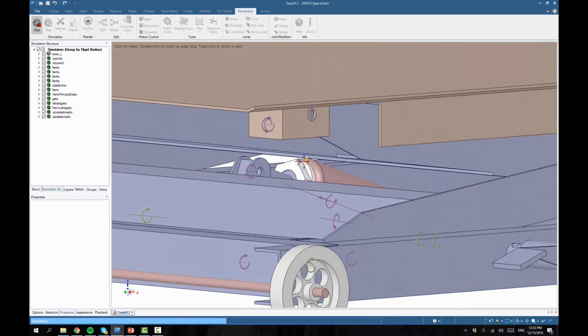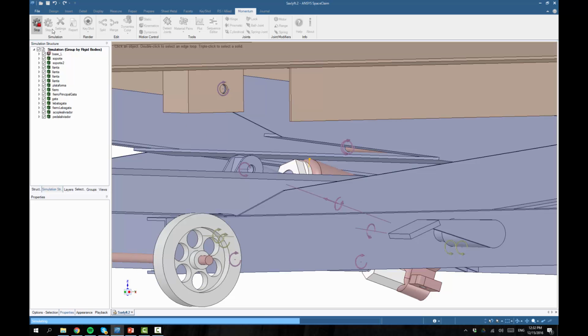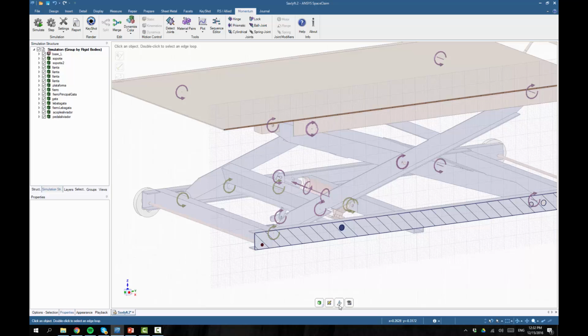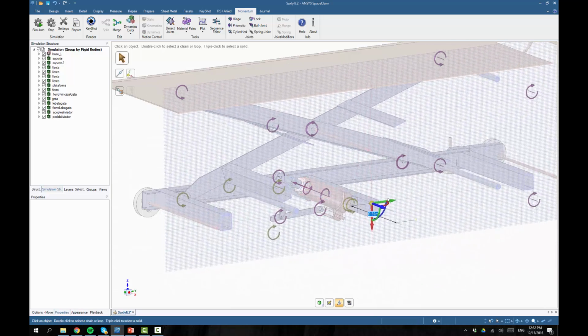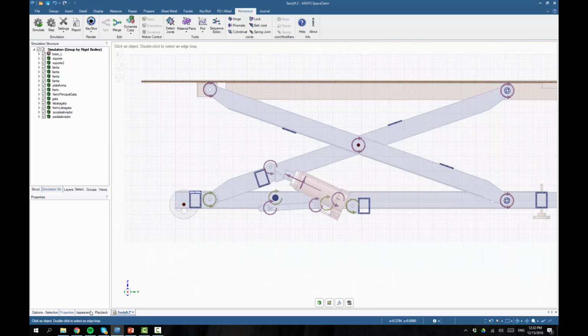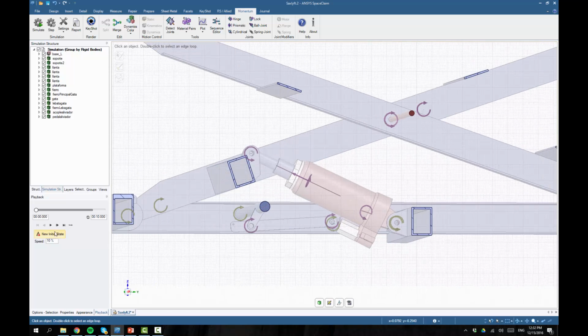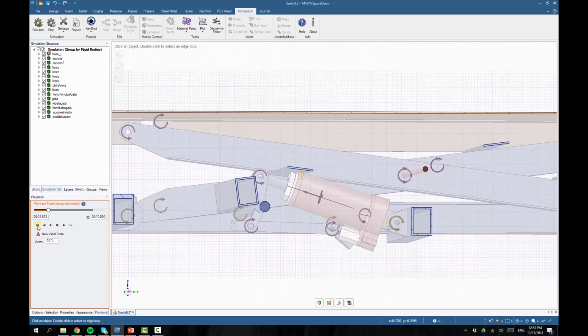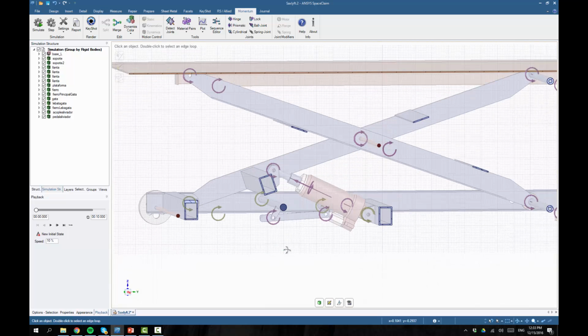Here is something that I'm not quite pleased about. See that bar lands on top of the hydraulic cylinder. Let's look a little more carefully at that. So let's just pull out this cross-section view. We can also watch the playback in slow motion. Now keep an eye on that beam. It lands directly on top of the hydraulic cylinder, and I don't think that's a very good thing. I would have preferred to have a more intentional mechanical stop in this design. And so, in effect, we have discovered an engineering mistake right there, without even looking for it.